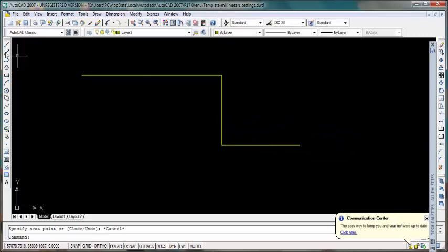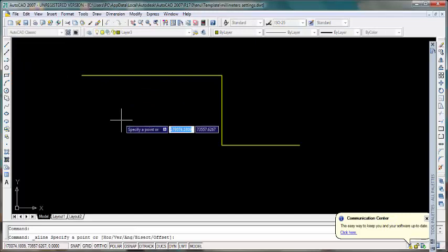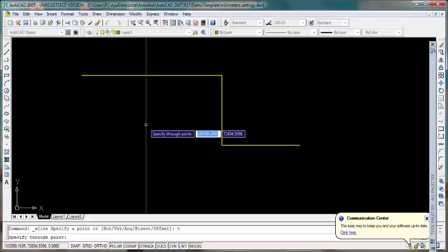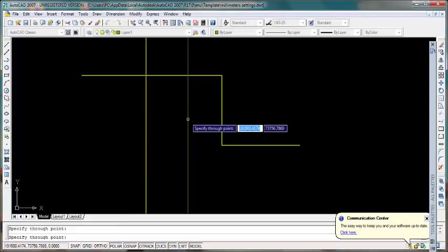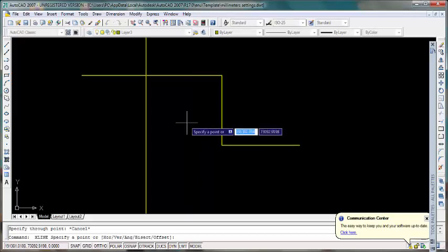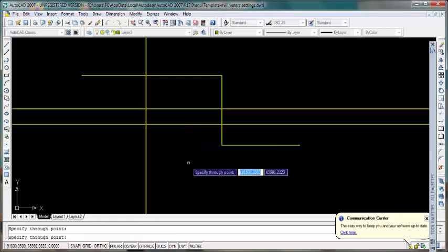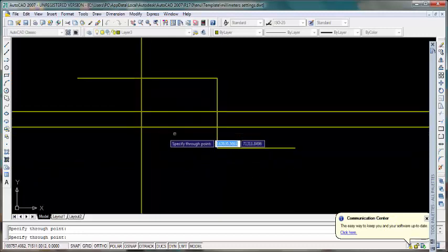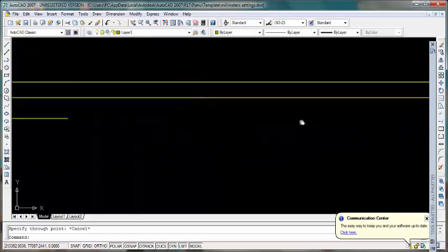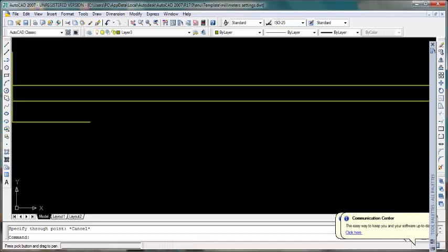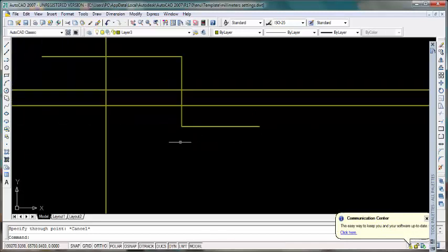We have the construction line. If you want to choose it vertically, if you want it horizontal, use the space bar to recall it. There are options here: horizontal, vertical, angular. You want it horizontal, click edge. Horizontal. These are construction lines. It's continuous, like endless. If you want to keep panning, you pan endlessly for construction lines.